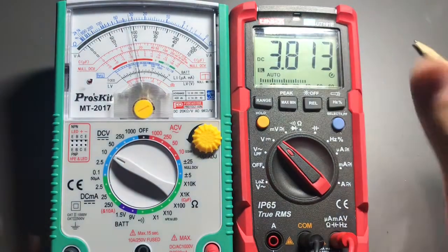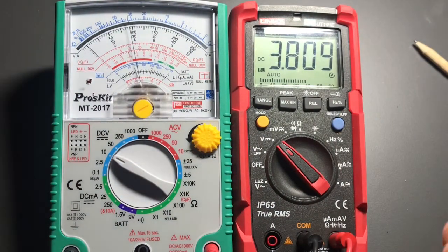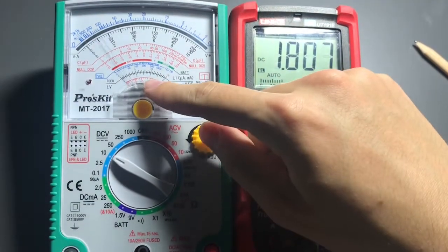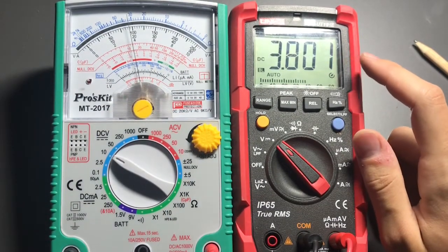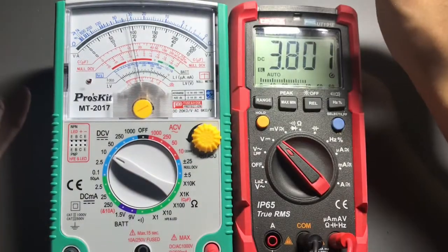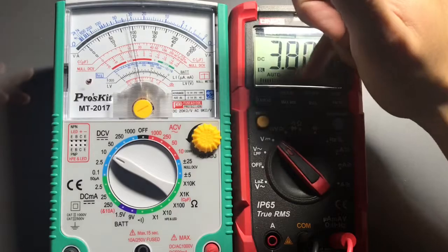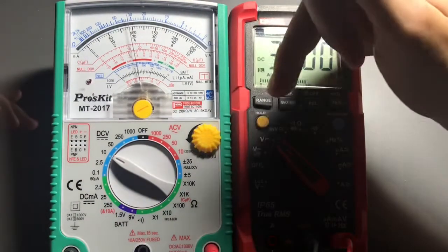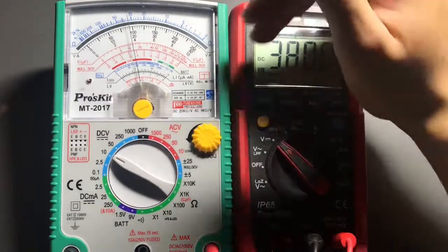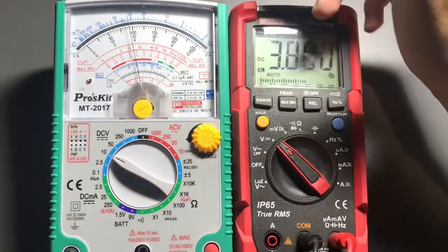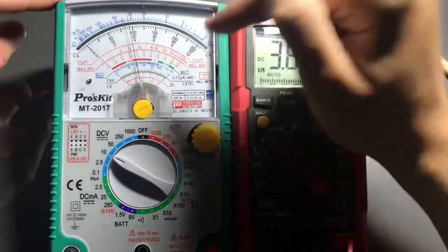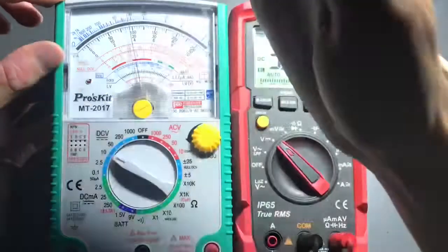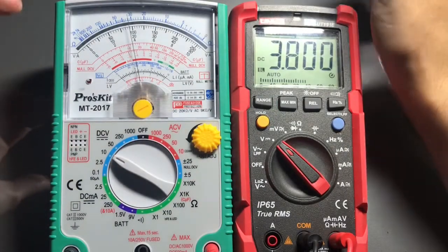So this is basically a comparison of these two. If I would show you a voltage that is oscillating, it is clearly visible here. And here, if I would, for example, connect a charging and discharging capacitor, for example a 555 timer circuit, it will need to rearrange in the middle. So I will need to put it in the manual range. And when it's rearranging, changing the range, there are zeros on the display, it rearranges, it finds the correct range and stuff like that. Here we have no problem like that, and we see the needle bumping around.